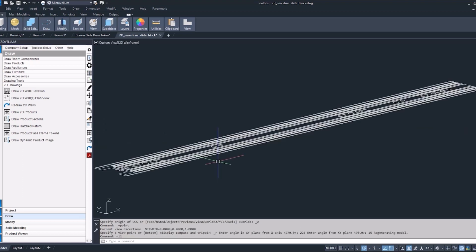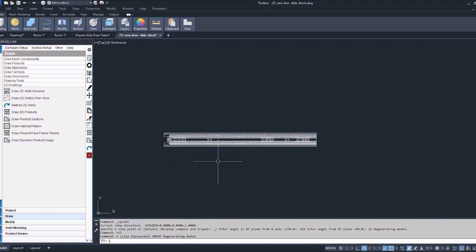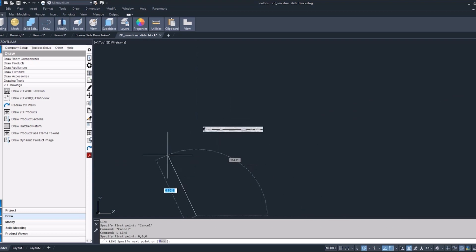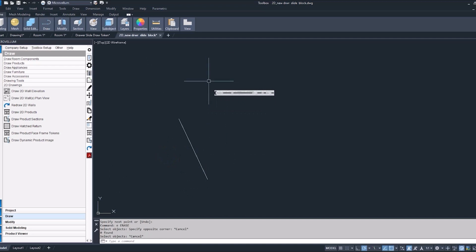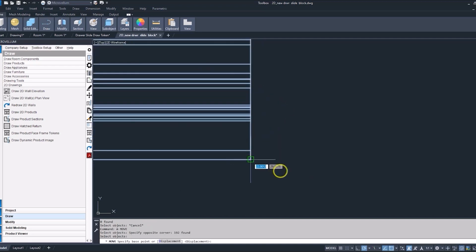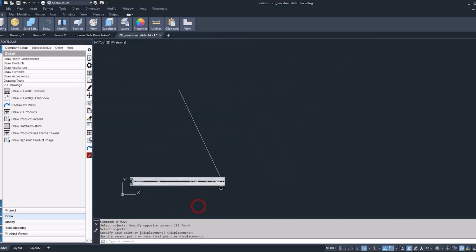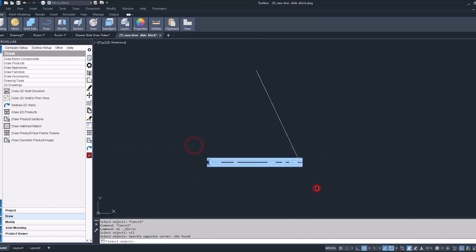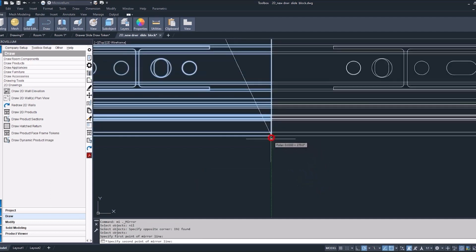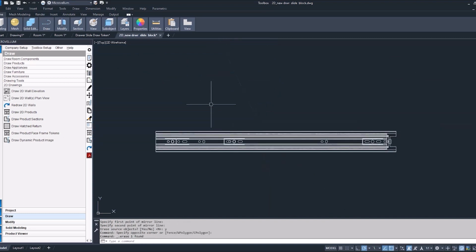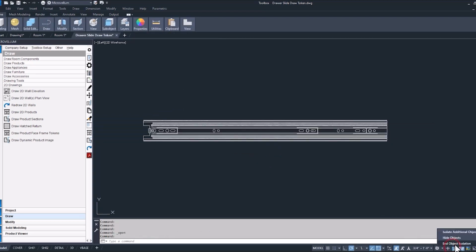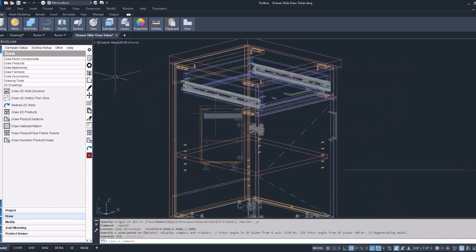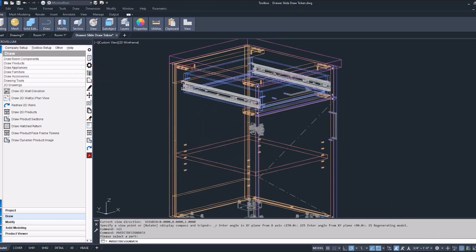It looks good. To double check our insertion point, I'm just going to draw a line and start it at 0,0,0. So that's going to be our insertion point of this drawer slide. Because I don't know exactly where we need it to be, I'm just going to move that corner to 0,0,0, and then do the AutoCAD mirror command so we have that drawer slide facing to the left. Okay, so now we've got that. Let's make sure we close and save that drawing. Back into our project, we'll end that object isolation, and now go into edit design data of the wood drawer box subassembly.